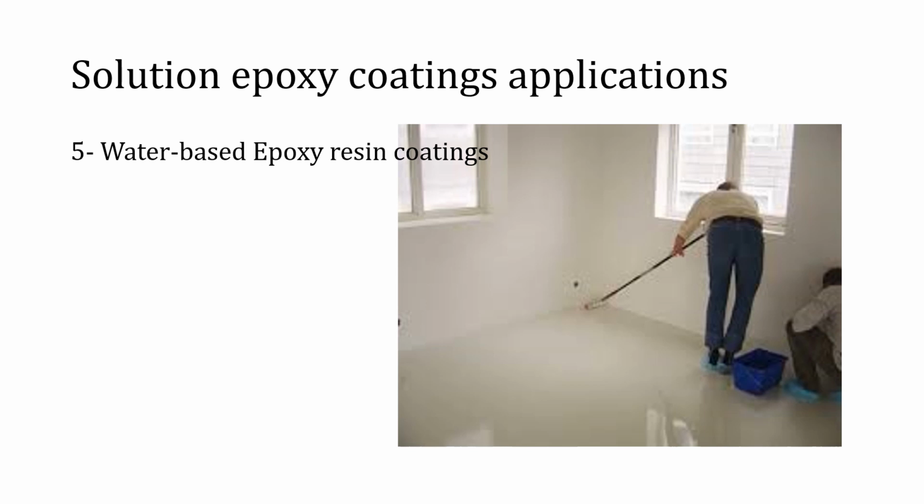Epoxy emulsions and other water-based epoxy coatings are also preferred in an attempt to omit the need of solvents and reduce the health risks associated to these applications. To produce a stable epoxy emulsion, often a suitable surface active agent is also employed in addition to the mechanical shearing, which is used to reduce the particle size of the epoxy in the medium.